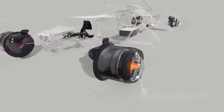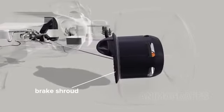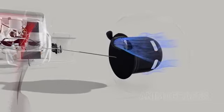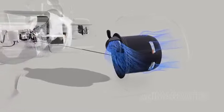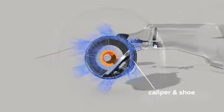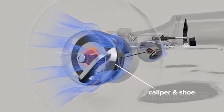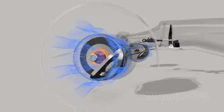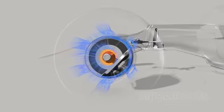Intense brake heat must be precisely managed, so the entire inner wheel assembly is covered by a ducted carbon fiber shroud. The front wing helps direct air into the brake ducts and through the inner wheel for cooling. The calipers are mounted at the lowest possible position for proper brake bleed. That is, ensuring troublesome air bubbles can escape hydraulic brake lines, while maintaining a low center of gravity.